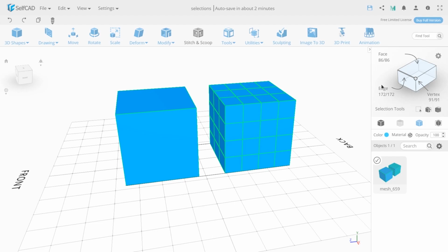Each of the modes in the control panel is signed with its own name: vertex, edge, face, and polygon. Go into the Vertex mode by clicking on the name or the corresponding icon in the control panel. The number of selected objects will be indicated by the first number. The second number will show the total number of vertices in this mode. When you select this mode, anchor points become visible in the workspace.